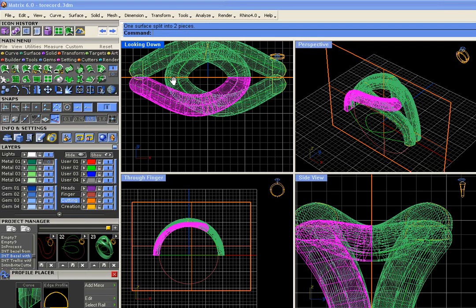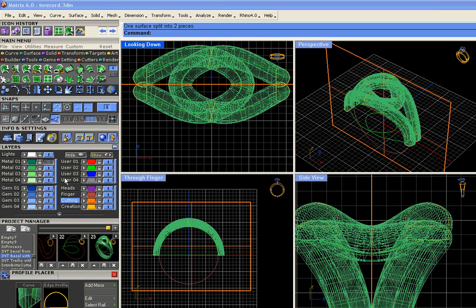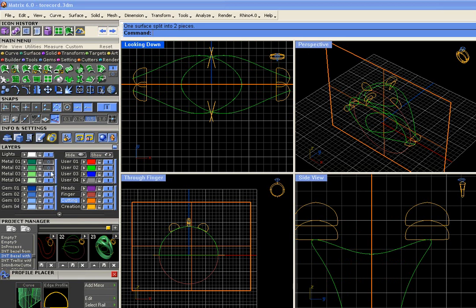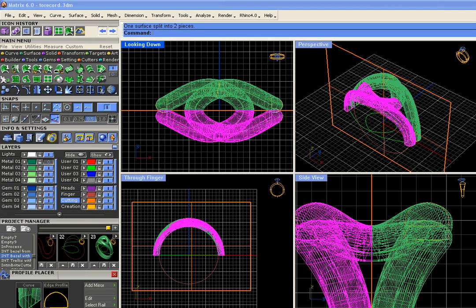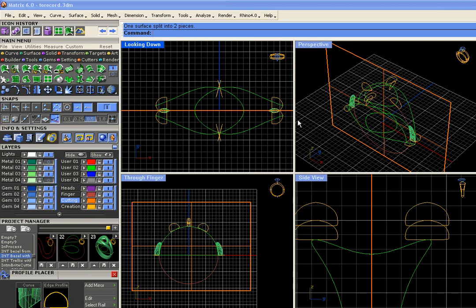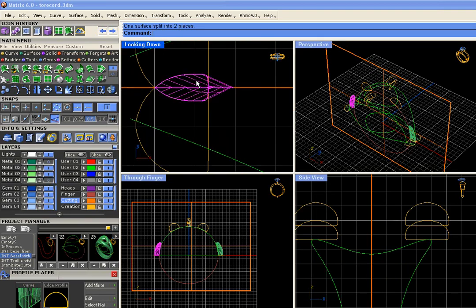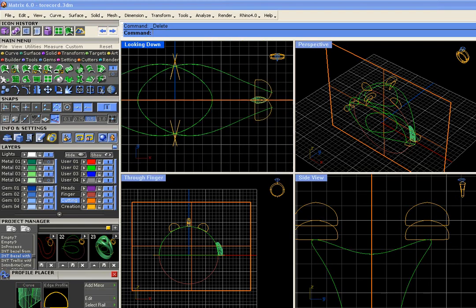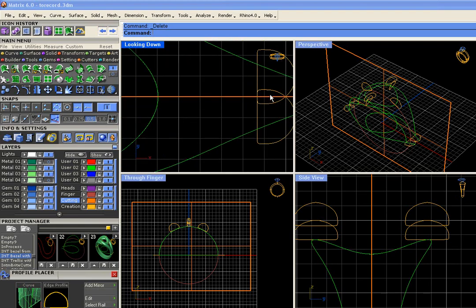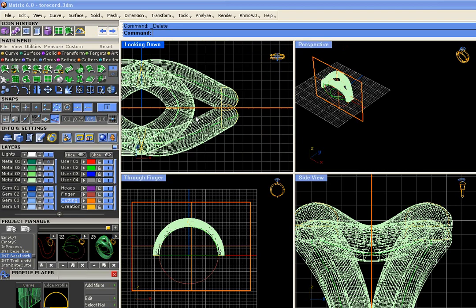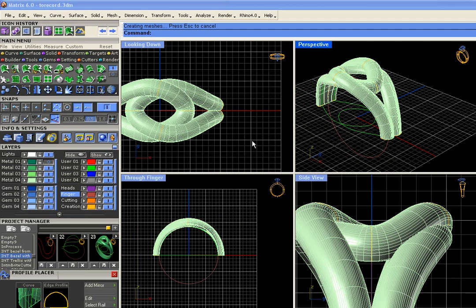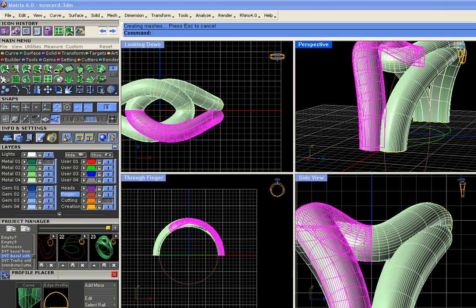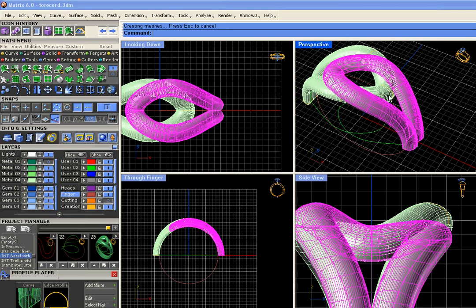Okay, and that's where this intersecting solid thing has a real problem. Rhino has the same problem as we do, and we can fix them manually. It can only fix them in its head. So let's go ahead now and take all the good pieces, stick them on another layer color, and just turn them off for now, and just take a look at what it left us. This little piece of junk, okay, two pieces of junk, and this little two pieces of junk. Now we can turn this back on. Let's shade it up. We can turn off our orange cutter. We don't need him right now. And join together both sides.